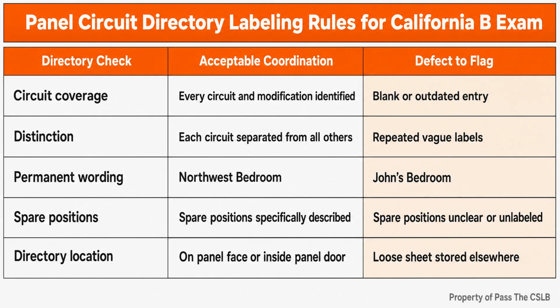At an electrical panel, a breaker number by itself does not tell the whole story. The circuit rating, the overcurrent protective device, the conductors, the load served, the directory, and the disconnecting method have to be coordinated by the electrical trade. My role as a general building supervisor is not to perform that design. My role is to recognize when the installation no longer makes sense as a coordinated system, preserve access, and get the qualified electrical contractor to resolve it before concealment, energizing, or inspection.